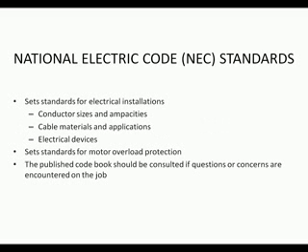External overload protection are devices that pass power to the holding coil of the starter or contactor. They open when an overcurrent condition exists. They're all done on amperage. The trip point and the type of overload protection are determined by the manufacturer. The overload device takes the service factor of the motor into consideration as well. Remember, the service factor is the additional capacity that a motor has.